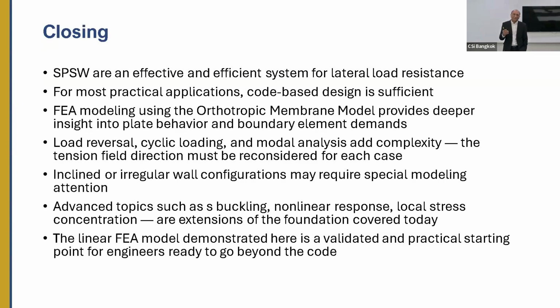But for most practical applications, the code-based design is sufficient as long as it falls within the unidirectional load distribution. The finite element model using the orthotropic membrane model provides deeper insight, as we have seen, into the plate behavior, boundary elements, and the demands, and then we can study a lot more from the same model in addition to just getting the basic forces.